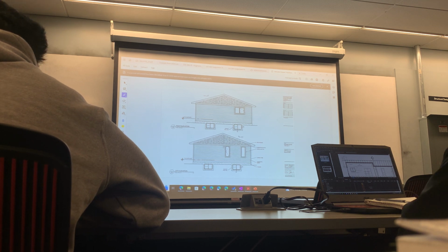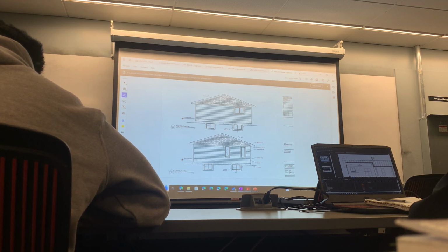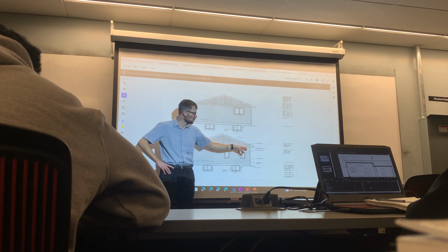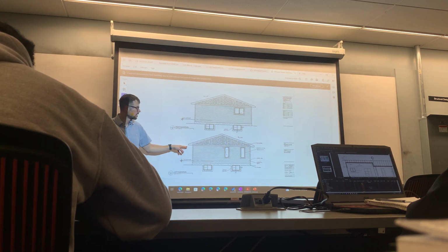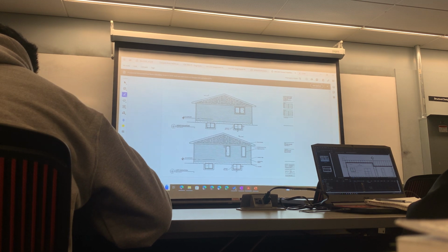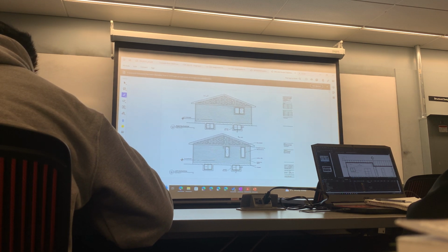would we have the same effective length for this wall? If you had a truss on top here, and you connected a wall at the bottom chord of a truss, what do you think is going to happen there? I'm not sure if the truss will be helping to resist lateral. That's the question. Can the truss do it? Let's use our highlighter here. I'm not sure, because then we would have K equals 2.